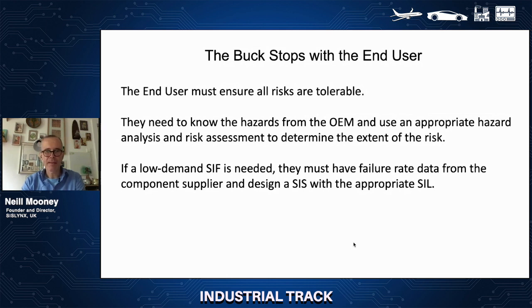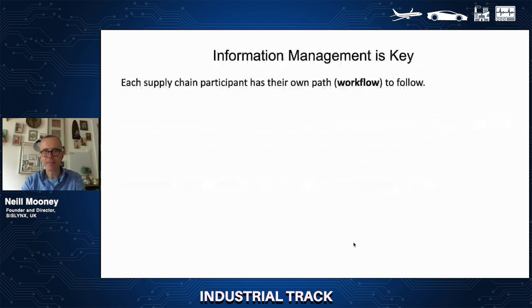If a low demand SIF is needed, they must have failure rate data from the component supplier and design an SIS for the appropriate SIL. So information management is key.